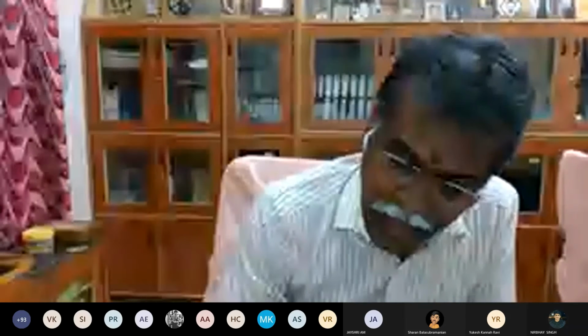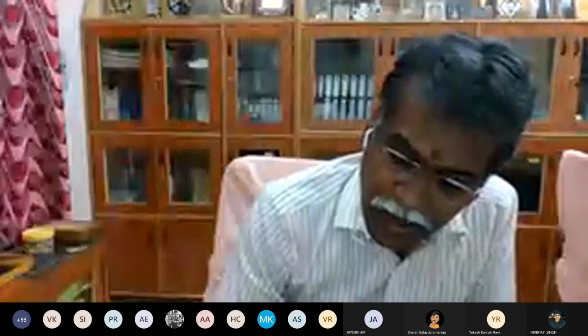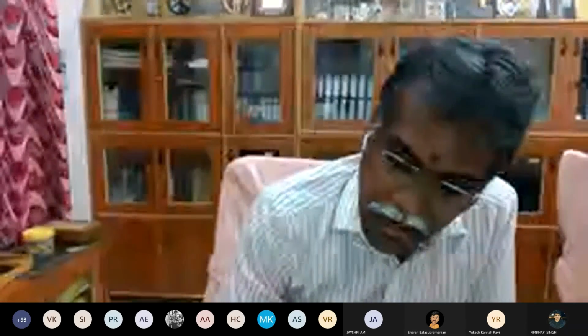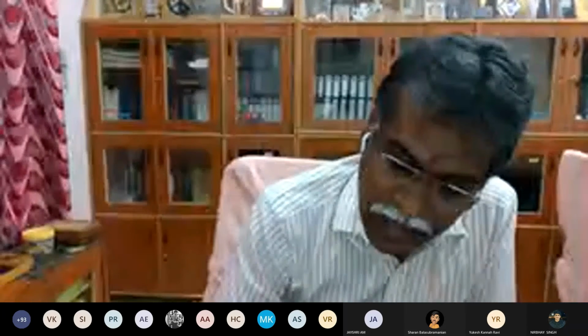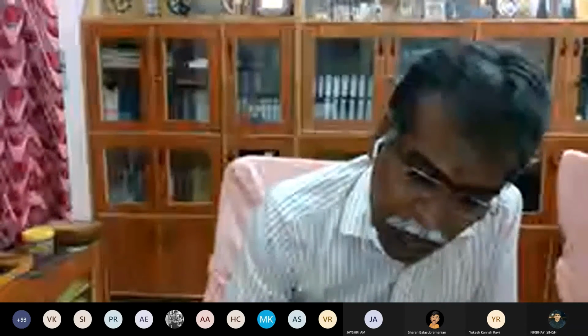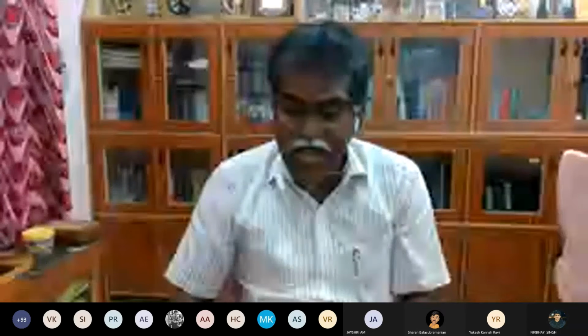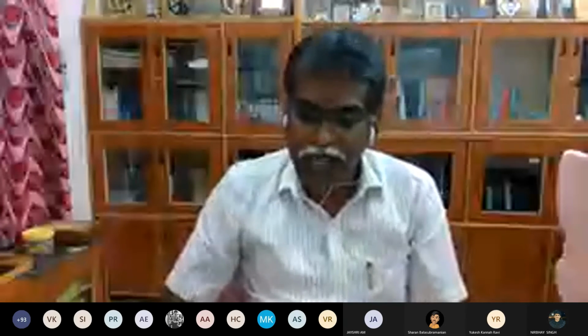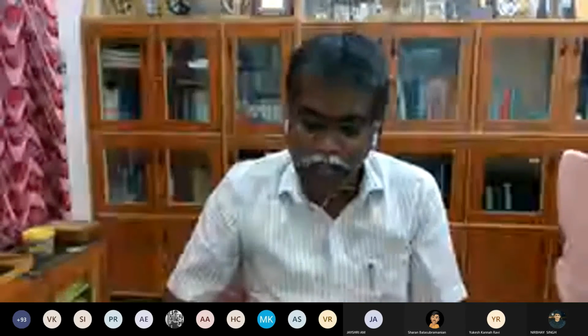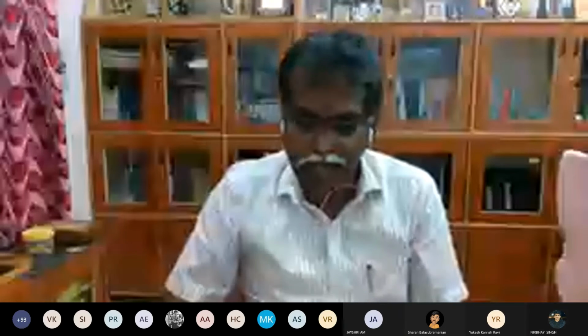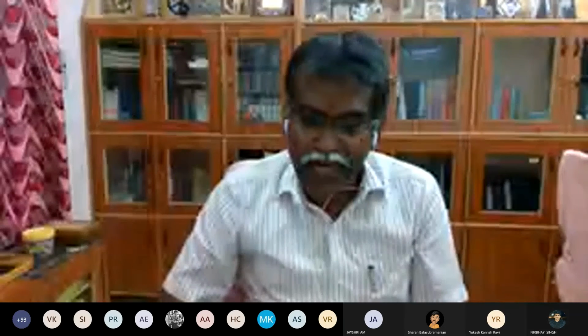So probably you would have come across the different units associated with turbidity: turbidity unit, Jackson turbidity unit, Formazin turbidity unit and Nephelometric turbidity unit. So these measurements you would have come across in the last semester. Okay. So turbidity unit is very simple. If you take 1 milligram of SiO2, dissolve it in 1 liter of water, it may represent some turbidity that you can measure in terms of 1 turbidity unit. So please make a note of this. Something important: standard turbidity, 1 turbidity unit is 1 milligram of SiO2 in 1 liter of water, which may represent some turbidity in water. That is called 1 turbidity unit.